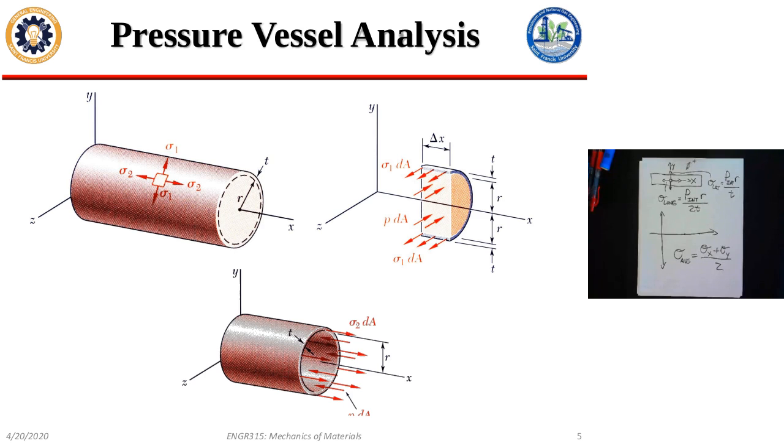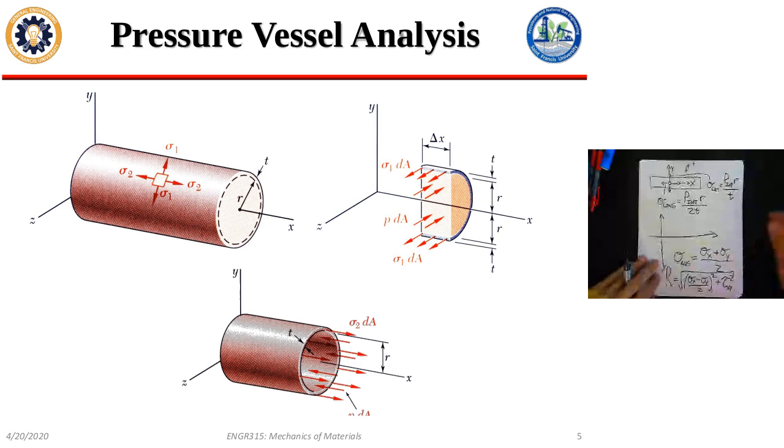What you're thinking about, I think, is the equation for the radius, which we're also going to need. That's the square root of sigma x minus sigma y over 2 squared, plus the shear stress squared. Let me rewrite this a little bit larger, though.